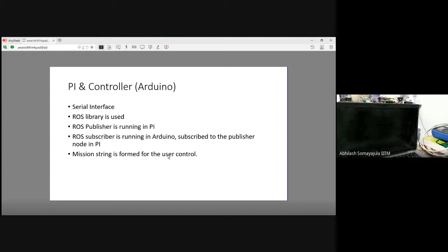Okay, so let's say you have a control node for obstacle avoidance, you have a control node for path following, and all like that. And then we will be having another one where we will merge it based on whatever we want in the field. Let's say, of course, the collision avoidance will be the prior task to do. So accordingly we do, and the only actuator signal which will be coming out of this, let's say turn, because the stepper will turn now. So that actuator signal will go to